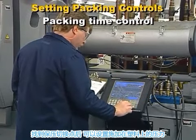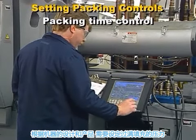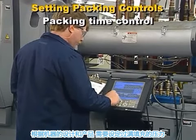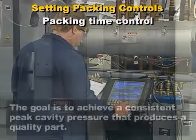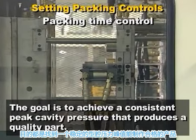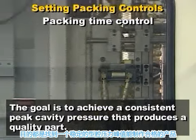After the transfer point is set, the controls to pack and hold pressures on the plastic can be set. To control the packing of the cavities, several different techniques are used depending on the capability of the molding machine and the desired part properties. But the goal of all packing techniques is to achieve a consistent peak cavity pressure that produces a part with the desired characteristics.